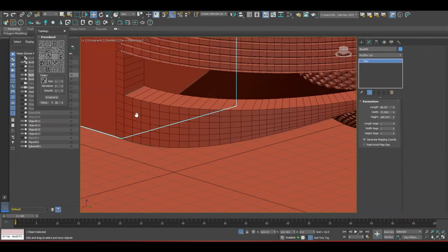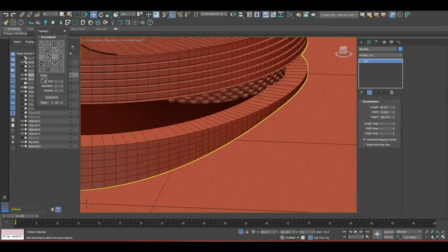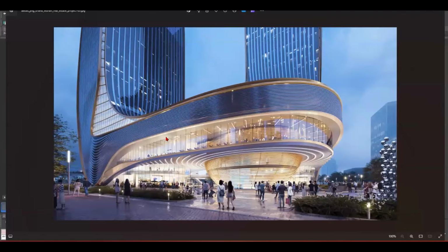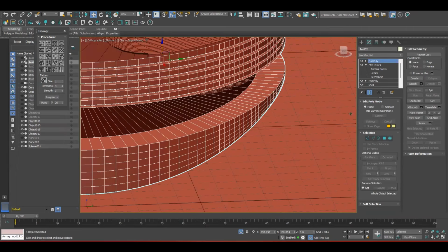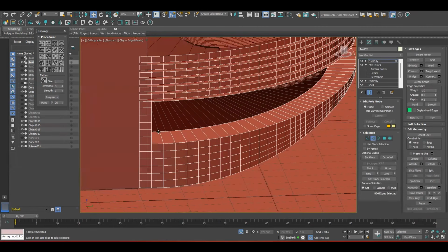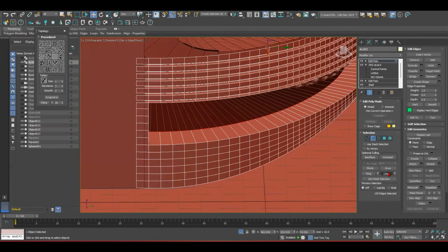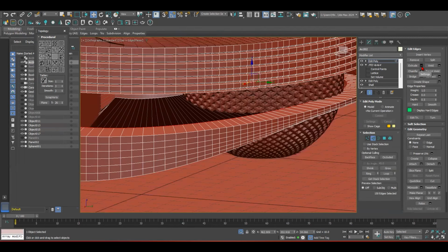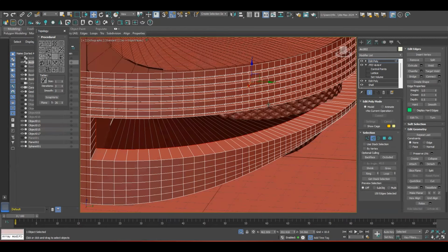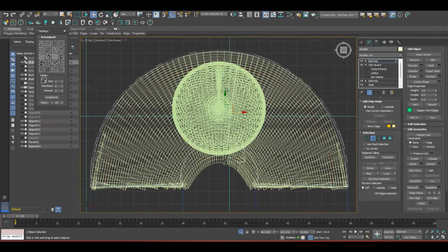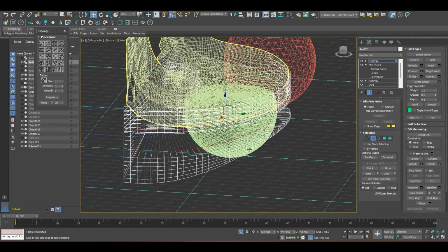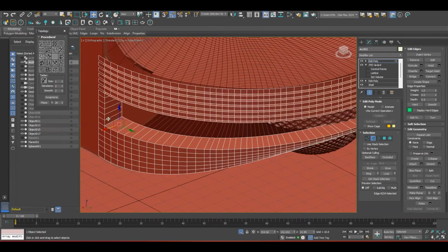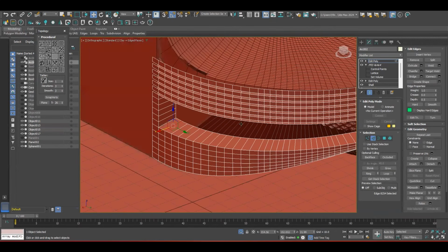So now we need to have the glass side here of this crystal mold. What we're gonna do, we can select one of the edges, we can do the roof, and we can do a copy of it. Instead of copy, we need to have another curve that comes all the way here.